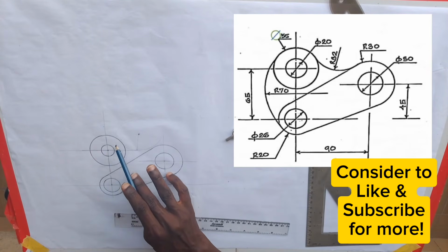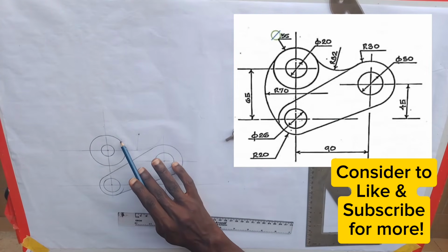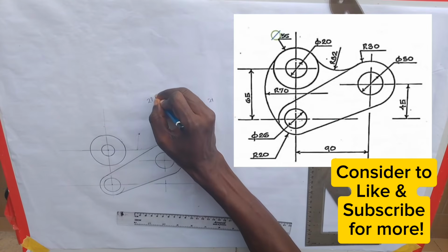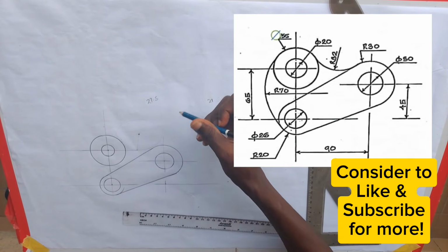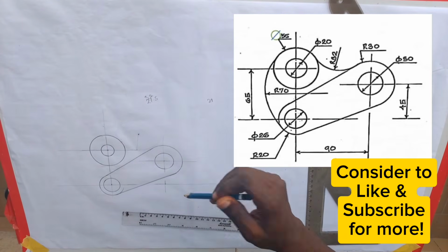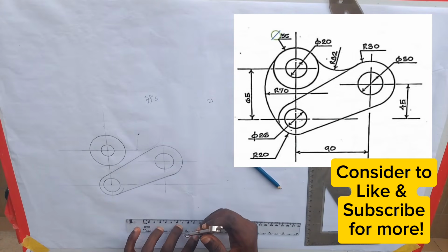So I add the radius of this bigger circle, from here to here, plus the radius of this external circle from here to here. You know the radius of this to be 27.5, and the radius of this external circle to be 32. So if I add 32 plus 27.5, what will it give us? That will give us 59.5. So I will measure 59.5 from my ruler.